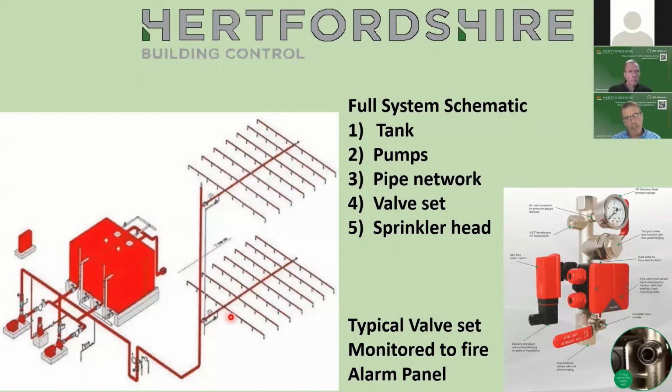Otherwise, this sprinkler here would discharge a lot of water, and this sprinkler here would discharge what it was designed to do, which is what you would design this sprinkler head for, about 1/2 bar. But you'll probably find you're getting 2 bar at this one, because you'll need 2 bar at this one to get 1/2 bar at that one. So that kind of gives you an idea of how things are balanced up.